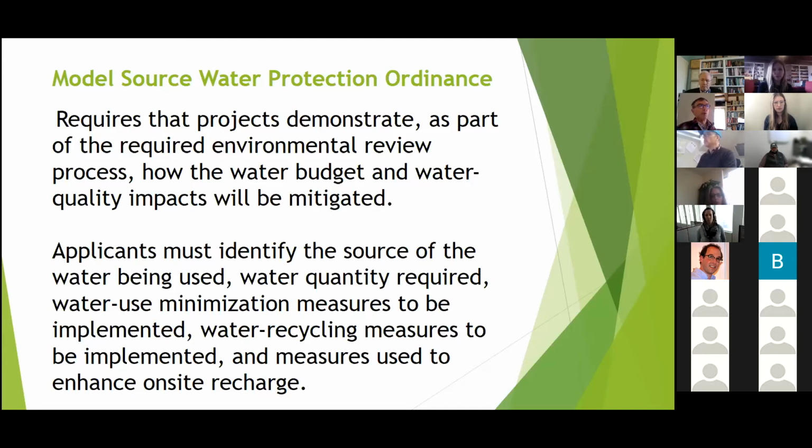What we were able to do once we identified aquifer recharge rates is, when you have that information, you can do project site by project site analysis on whether a project is sustainable or self-supporting, which is not a requirement, but is a useful piece of information as you go through the SEQR process and can help you understand whether there may or may not be offsite impacts. So we can look at a 50-acre parcel, for example, understand what the typical recharge rates will be, and then calculate the water uses that are proposed for that parcel, not just the pumping rates, but more importantly, probably the consumptive water uses, which are usually just a fraction of the pumped water, and then determine whether there's enough recharge on site to support the consumptive uses.